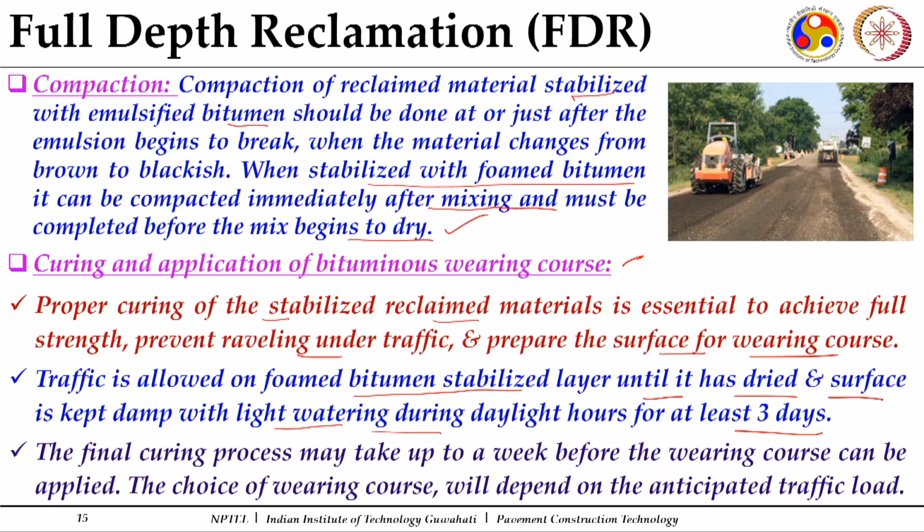Depending upon what type of stabilizing additive you have used, lime or cement, and the content, we may have to go for a longer curing period, maybe 1 week. So, the final curing process may take up to a week before the wearing course can be applied. This is very important, otherwise if proper curing is not done and the wearing course is applied, the wearing course will get damaged and stripped. Your base course will not have achieved the required strength, and if traffic is allowed after the wearing course, this will immediately lead to premature distresses in the stabilized base courses.